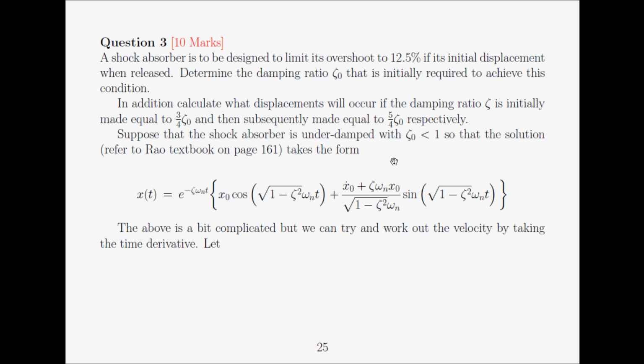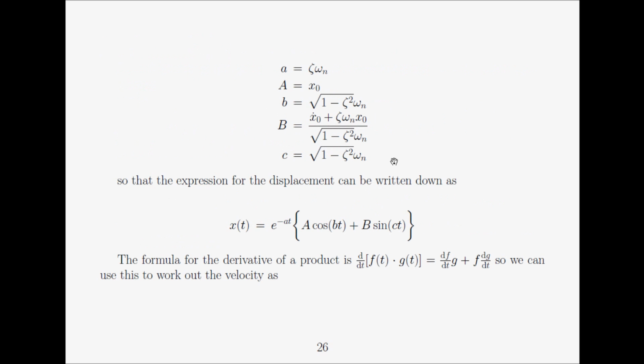Very quick comment over here. When we have a mass spring damper system, which is essentially the vibration system that we'll be looking at in this course, the parameters or constants of mass m, spring k, and damper c, these three quantities are essentially equivalent to zeta, the damping factor, and omega n. We'll see how this happens at a later stage when we go through the course. In any case, in this particular equation, zeta and omega n contain the same information as m, k, and c. So let's see how we can do it.